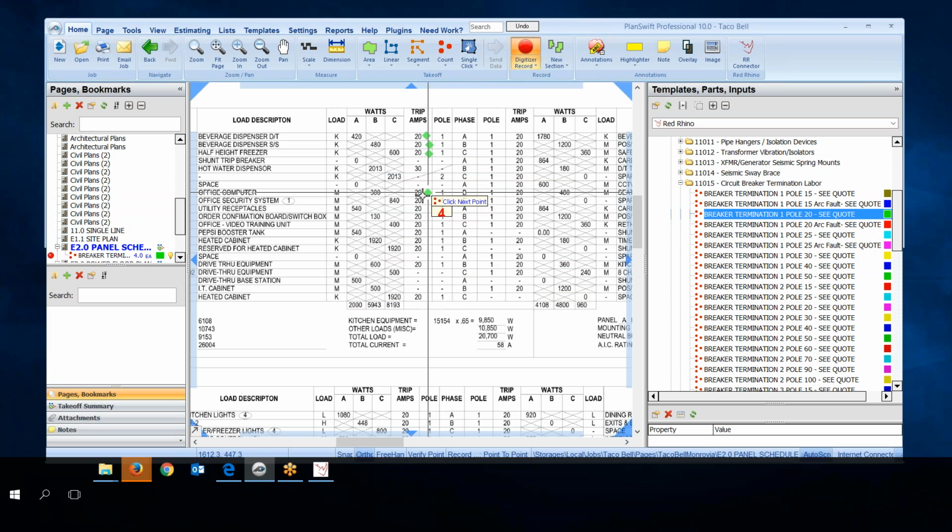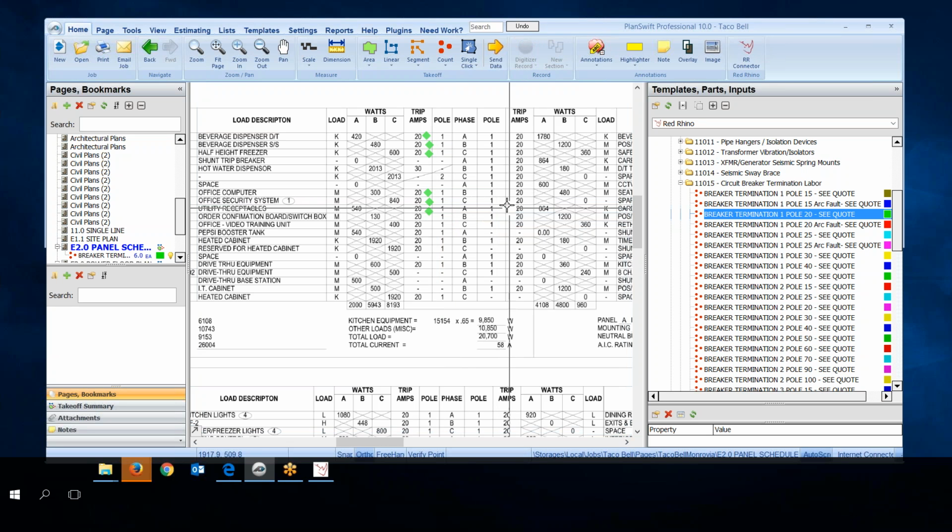Okay. As I do, again, it digitizes over here, shows the count, as well as showing the count on the screen. Okay, now in this case, I'm going to right click and I'm going to stop, but normally I'd go through this whole page and count all these circuit breakers for estimating an input. Now I'm just going to go now and find a 2-pole 30 amp.